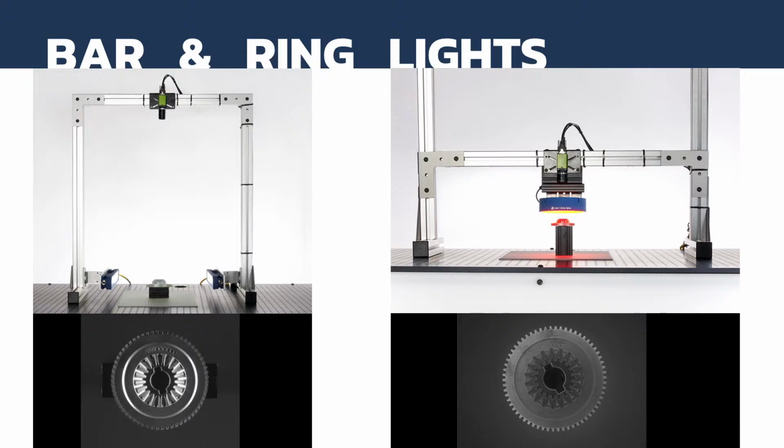So this is a case where the object dictates what is right between these two form factors. So for a circular object like this with surface details that we need to capture in a dark field setting, the linear lights work okay and you might get by with it, but it's not great. If I were going to continue in a linear light setup with that kind of scenario, I would probably use 4 linear lights at 90 degrees to make a perfect square or rectangle around the object. At least then we're getting equal reflection, 360 around the object, and we could probably get a pretty good dark field image in that case.